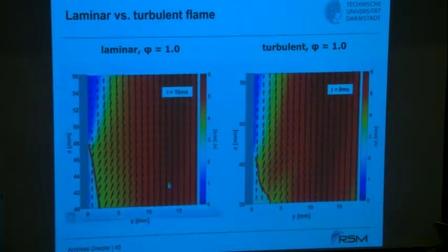In the turbulent case, now you have this grid installed. Everything is more dynamic. At the same equivalence ratio, you see here the flame quenches further upstream. Of course it changes with time. You see the wrinkling is reduced. It's getting laminar, like in the head-on quenching, although it's not too turbulent. The turbulence level is around 6 to 7%.